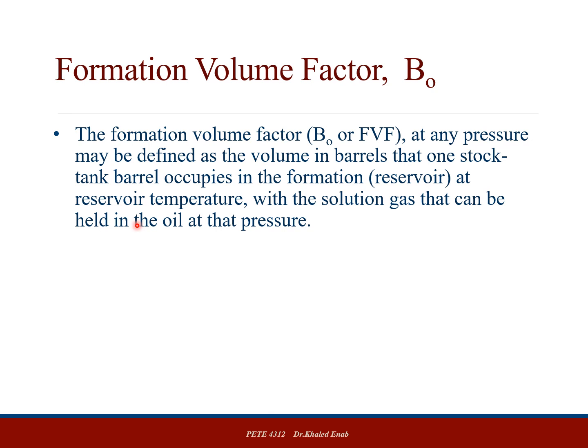This is different from the Rs, or the solution gas ratio, because the solution gas ratio tells you how much gas is dissolved in the oil. Formation volume factor tells you how much of this liquid in the reservoir would be represented on the surface. Okay, so if I have the Rs of the reservoir under 1000 psi, I know how much gas is dissolved in this oil under 1000 psi. When I produce it, this gas will be released.